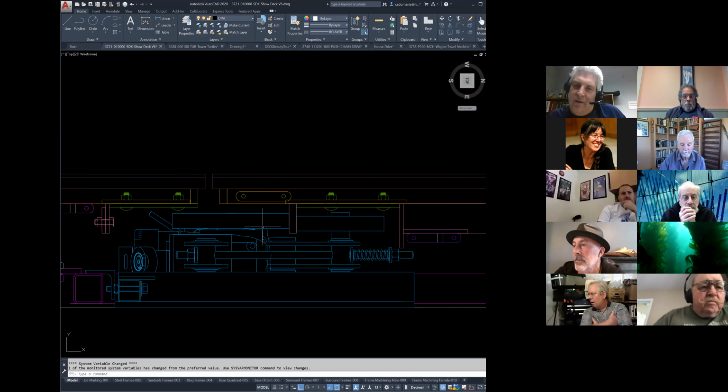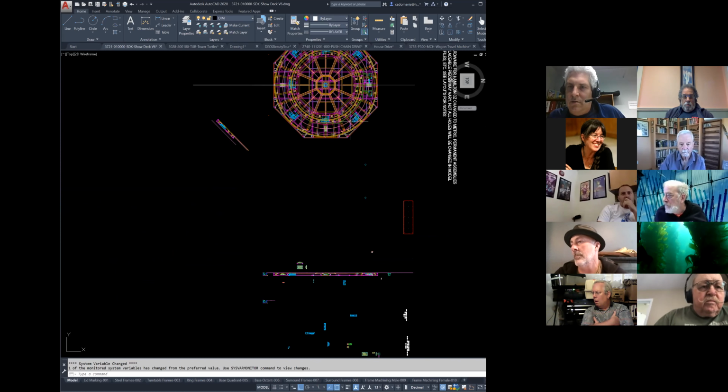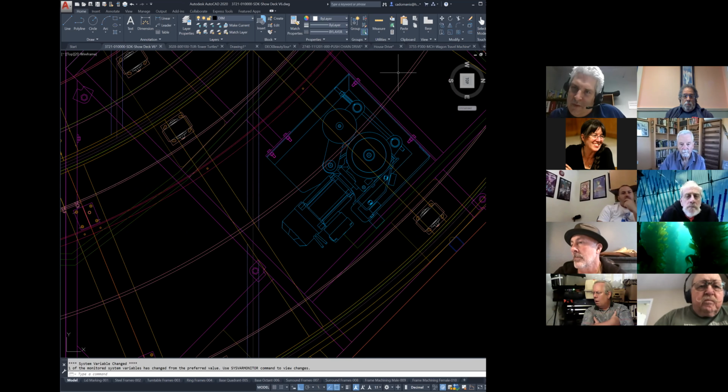That same style fin that goes around is being driven by this pinched friction drive system. So we have a gear motor with a friction wheel directly on the output. And then we have a pinching wheel that uses spring tension to generate some friction between those. And the clever detail here, and all of that you can see: this pink circle is the drive frame, and we have our friction motor here and our opposing friction wheel, and that's that tensioned line.